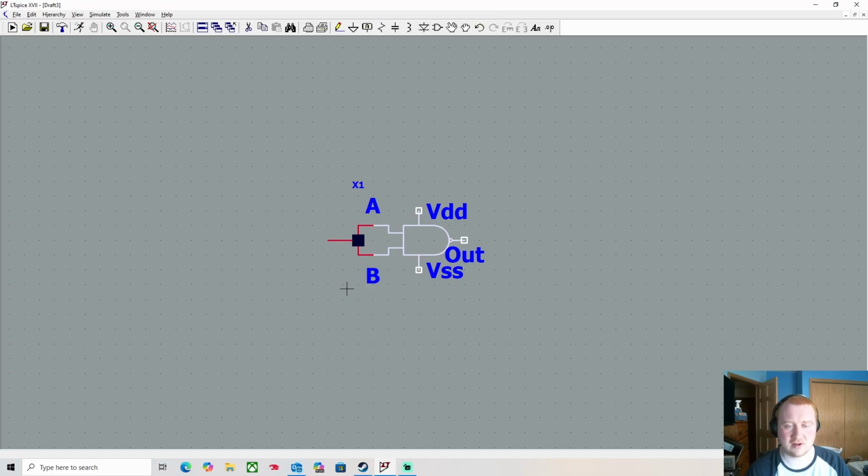The reason that this works is, if you were to provide a 0 on the input side, both zeros make a 1 for a NAND gate, so 0 to 1. And since 1 and 1 NAND gives you 0, it's 1 to 0. That's literally all that you have to do. We need these as well, everything that we needed before. And our output.